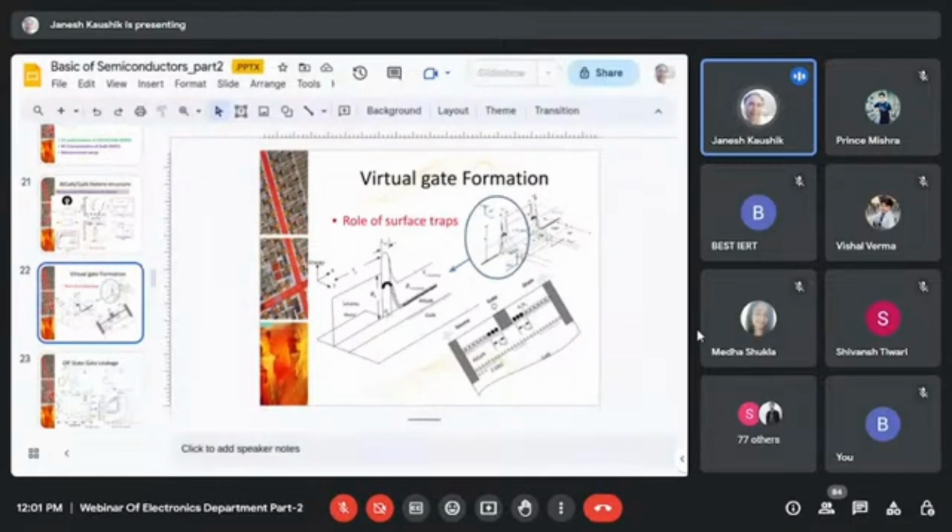And one more thing which we use in gallium arsenide technology, which we can't use here, is a gallium arsenide highly doped layer at the top surface of the AlGaAs layer. But here we can't use that because gallium nitride substrates are not so available. Whatever is available is in small sizes and very costly, so we use non-native substrates, like silicon carbide, silicon, and sapphire. But this heteroepitaxy gives rise to defects. Those defects propagate right from the substrate to the epi layer to the top layer of our device geometry.